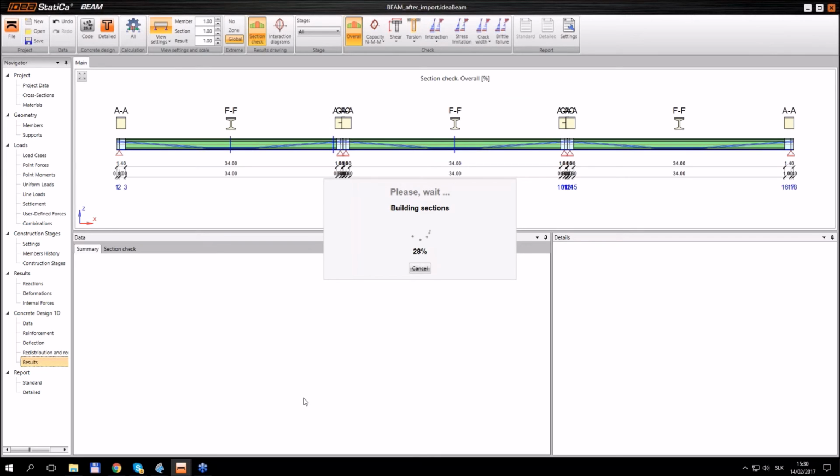All the checks are done in nonlinear calculations. Even the calculations for SLS checks are nonlinear because of the cracking. According to Eurocode, we have to respect when the crack appears, and then we disregard the concrete in tension. So that's why we do it. Okay.